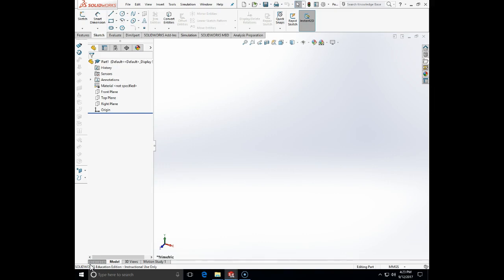However, many times when we design new things, like a new product, we do not have all the parts ready. But we can start by designing, for example, the overall shape of a mouse or the overall shape of a car, and then carving out from that master model, building the new parts. That approach is called the top-down approach or top-down assembly. Most of the time we combine the two, because you will have some parts ready, especially standard hardware, parts that you buy, but then you will have some parts that you will need to design to fit the form and function of the project.